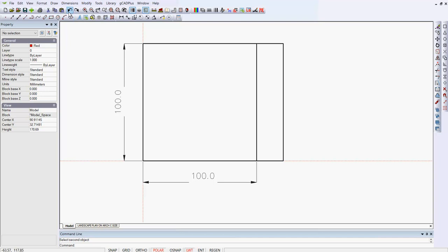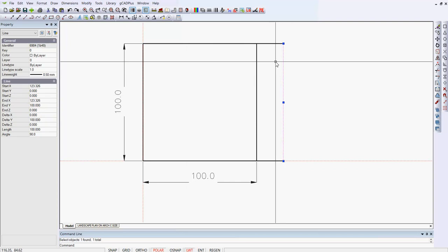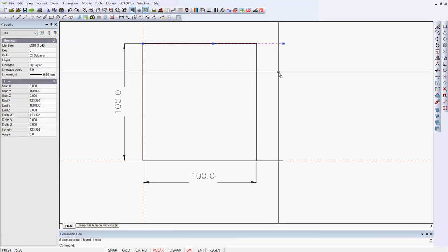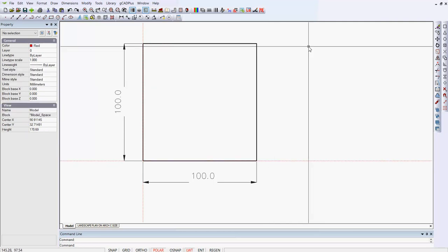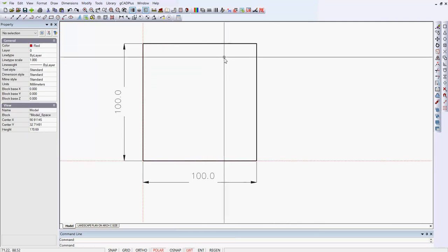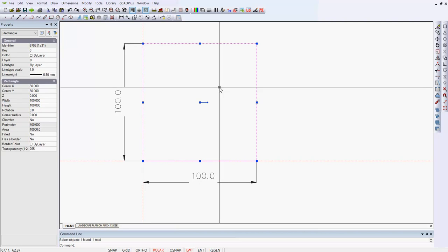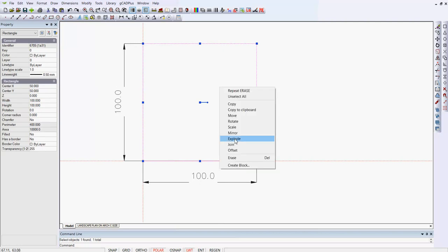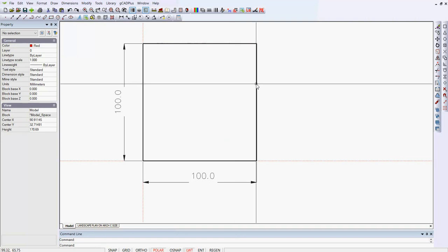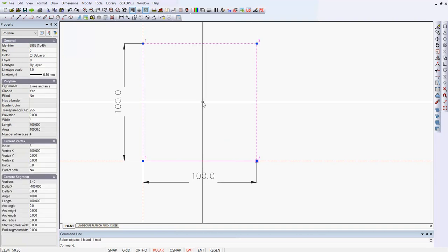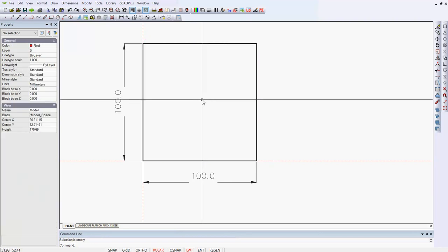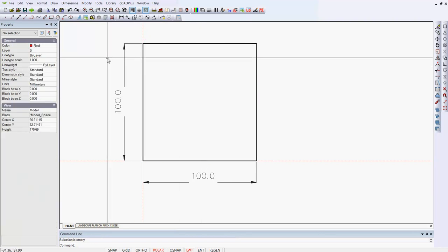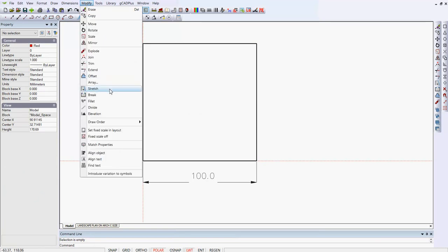Let's see if we can revert back and remove that, and that line can be removed and this one can be removed. That's as a result of the fillet command. So we're now back to the original rectangle. So one right click, one left click on explode, and we've broken it up now into that sort of standard polyline with 4 segments in it. What I can then use, if we want to achieve his aim, is to modify and stretch.